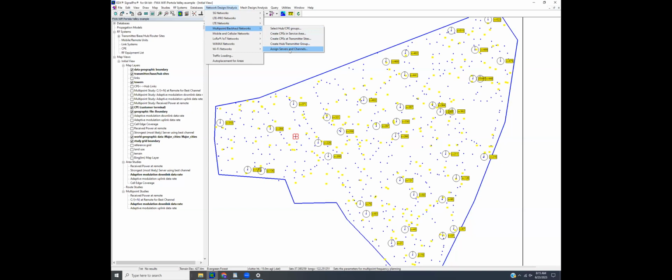We should also point out that we have automatic channel assignment functions, both for multi-point fixed assignments or across an entire area. If you want to assign channels to your APs in the best pattern to mitigate any potential interference, you can do it that way on an area-wide basis. I'm sorry, that automatic frequency planning would be here under Wi-Fi if we're doing that for an area-wide basis. Or if we want to do it for a fixed network, we can do assigned servers and channels here under multi-point.